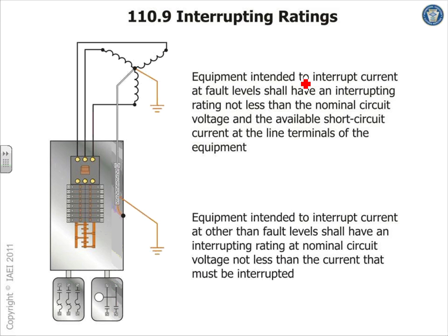So a long story short, guys, when you have a ground fault, your equipment must be able to handle the ground fault, and your circuit breaker must be able to handle the short circuit and the ground fault enough for circuit breakers to open. Your equipment has to be able to withstand the mechanical magnetic stress that the ground fault imposes on them, and the heat from a ground fault or a short circuit, withstanding enough for the circuit breaker to trip.